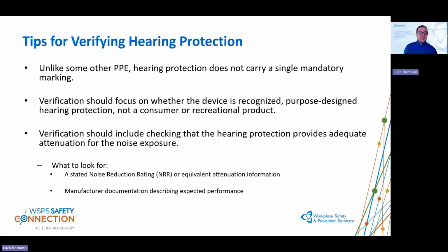So, take a look at the noise reduction rating or the equivalent level of protectiveness that it provides, and cross-reference it with manufacturer documentation. Do they have laboratory data to showcase that it's been tested and, in some cases, certified to protect at different frequencies or levels of noise? So some type of performance data for the most part.